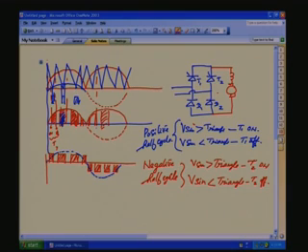How the frequency components are shifted in sine triangle PWM, we will come to that at a later stage. But here we have to know that the next higher order harmonic is not the fifth, not with respect to the fundamental, it will be with respect to the triangle frequency. So, if you use a higher triangular frequency, the harmonic currents drawn by the load can be reduced. But the problem is with the thyristors. Thyristors require external turn off circuits. So, high frequency PWM may not be possible with thyristors, but with presently available IGBTs, we can have high frequency PWM.